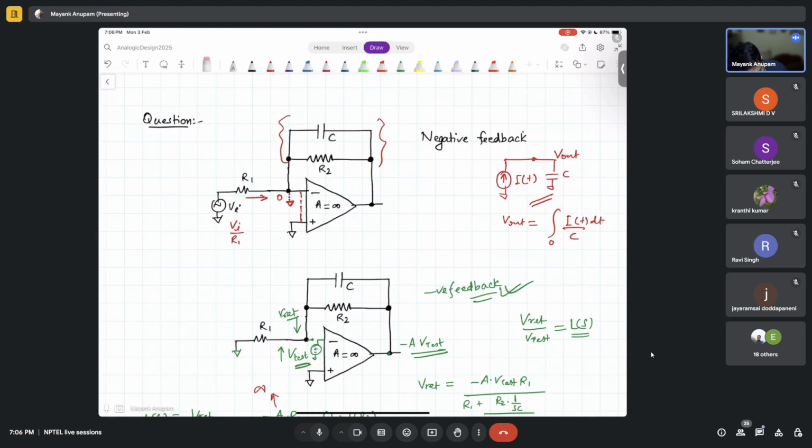Yes. So even in the presence of this resistor here, there will be a DC term, a gain term associated with I times R. It will behave like a first order filter. It's an integrator only, but it will behave like a first order filter, something of this kind. Got it? So there will be a pole here. That pole will be equal to 1 over RC. So I hope you know all of these things from your basic circuit analysis, right?